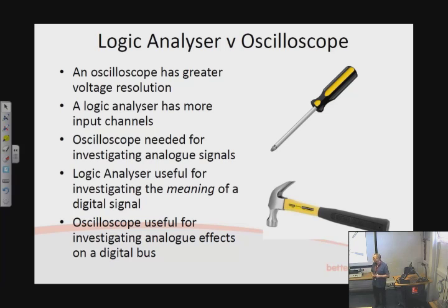And so you have your oscilloscope to satisfy yourself that the data is being transferred correctly. And then your logic analyzer sits above that, confirming that the data is meaningful. In other words, the data is useful information being transmitted. So hold those two thoughts, and bear in mind which tool you would use for which situation.